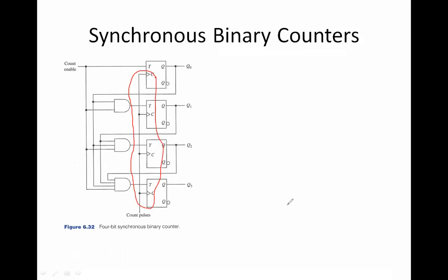So what will happen because of this? Changes can happen simultaneously, right? Now there is an interesting thing here, where the count enable is also connected to my AND gate. If my count enable is 0, which means 0 directly gets in here, and then here also it is 0, my output is also 0, which means my flip-flops will never work. Never work means there is no data entering, there are only zeros, right?